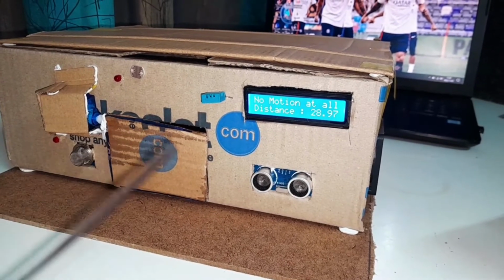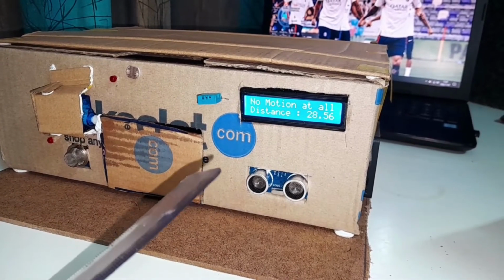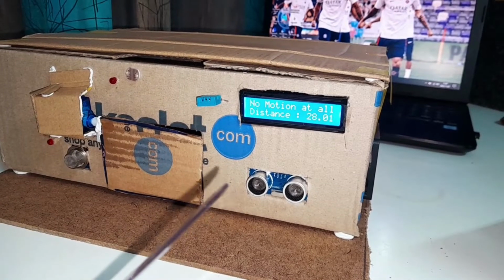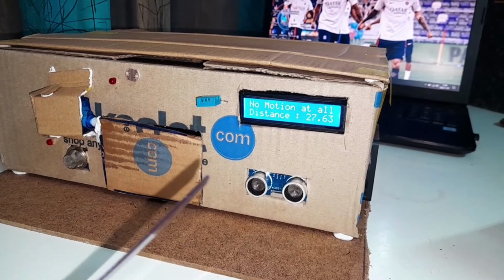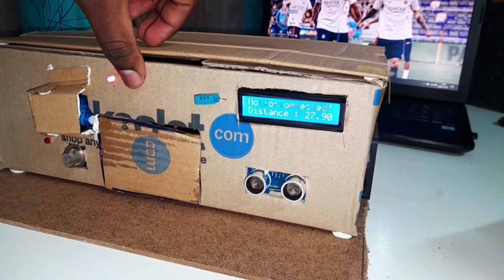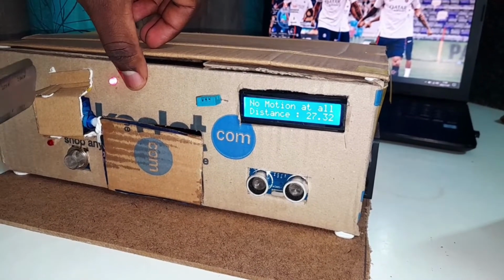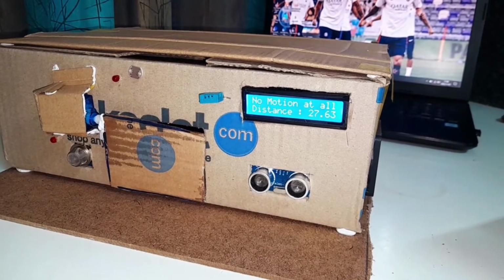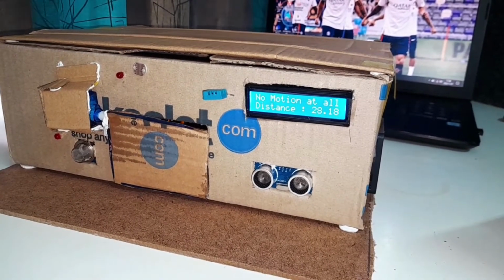This is an LDR sensor. An LDR sensor detects between day and night. So when it's dark inside the elevator, the relay module inside the enclosure triggers the LED to be on. It's dark, the relay module triggers the LED to be on. Then when it's bright, the relay module triggers the LED to be off.